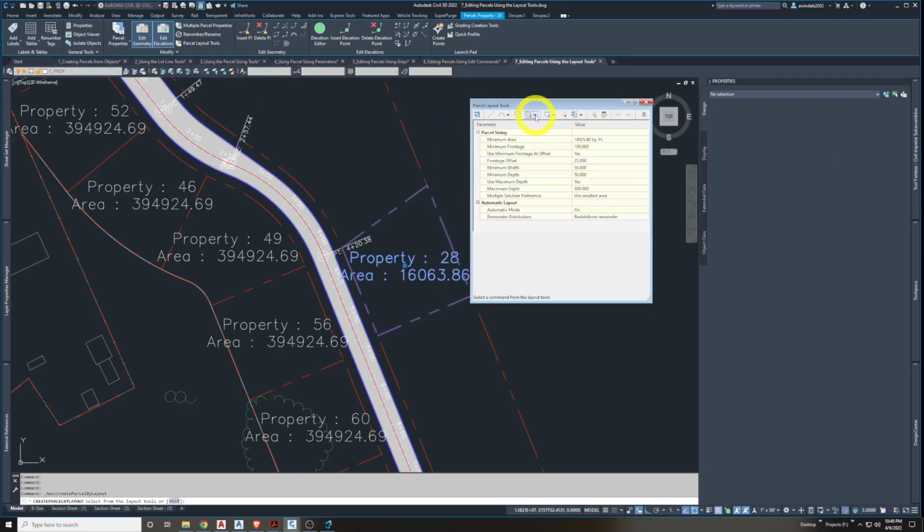We're going to go into here to say, I want to edit a slide line or a swing line. The freeform create is pretty easy to edit because it has grips. You can move the grips wherever you want once they're made. In this case, let's type in some parameters. We'll start with the minimum area. Instead of square footage, I'll put 0.05 and physically type in acres. So that should look like that in square footage.